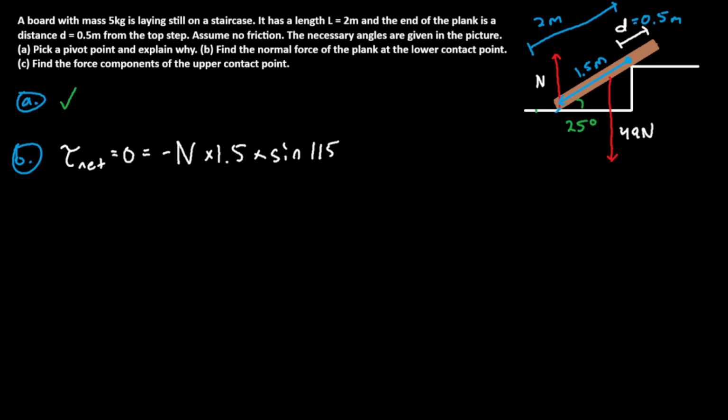So if we write down the formula for the torque, it's 49 newtons as the magnitude of the force, and it's positive since this force technically rotates the plank in a counterclockwise direction about this pivot point, so it's going to be a positive torque. So 49 times your distance. So how do you calculate the distance? Well, using a little bit of arithmetic, you can calculate the distance.